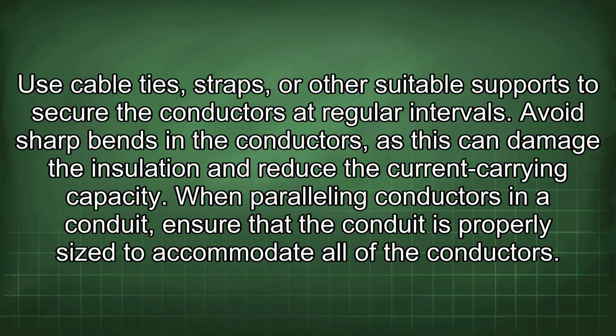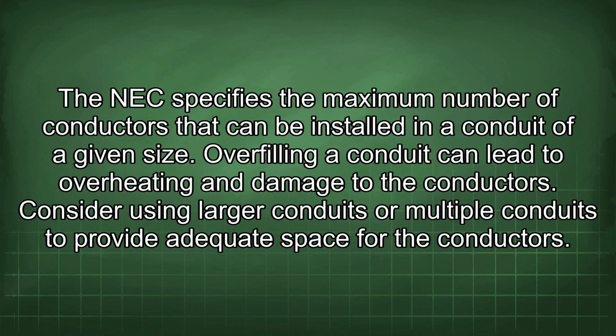When paralleling conductors in a conduit, ensure that the conduit is properly sized to accommodate all of the conductors. The NEC specifies the maximum number of conductors that can be installed in a conduit of a given size. Overfilling a conduit can lead to overheating and damage to the conductors. Consider using larger conduits or multiple conduits to provide adequate space for the conductors.